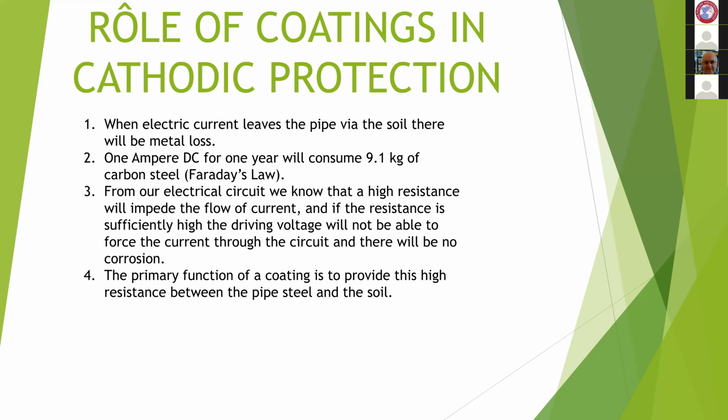Modern coatings, properly applied, are significantly better than the coatings we had even 10 years ago, and certainly the coatings we had 50 years ago. But of course, we've still got a lot of pipelines around that are over 50 years old with coatings that are of that age too. So they're probably past their best now. Some of them will be totally transparent and will demand large amounts of cathodic protection current. But we can deal with that retrospectively, provided that there are no other obstructions to the current getting onto the pipe.